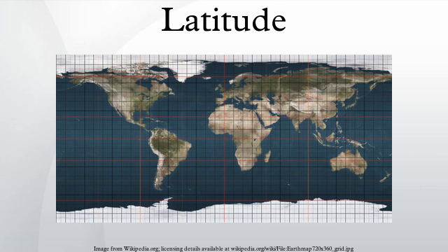The graticule formed by the lines of constant latitude and constant longitude is constructed with reference to the rotation axis of the Earth. The primary reference points are the poles where the axis of rotation of the Earth intersects the reference surface. Planes which contain the rotation axis intersect the surface in the meridians, and the angle between any one meridian plane and that through Greenwich defines the longitude. Meridians are lines of constant longitude.